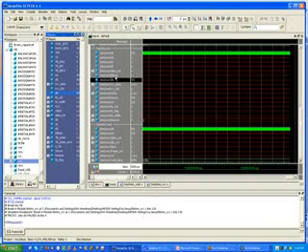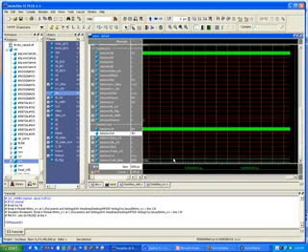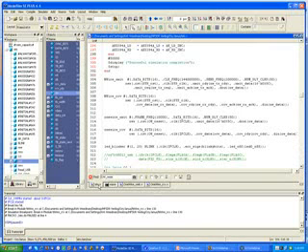So now we have to figure out, why am I getting all these unknowns? Let's take a look at some of these signals. First thing you want to look at is, do you have a clock and do you have a reset? Well, the key here is my reset is unknown. So now we have to find out why it is unknown. So I go back to my simulation. I see, okay, here's my reset right here and here. I've got them both, but let's go look and see where it comes from.